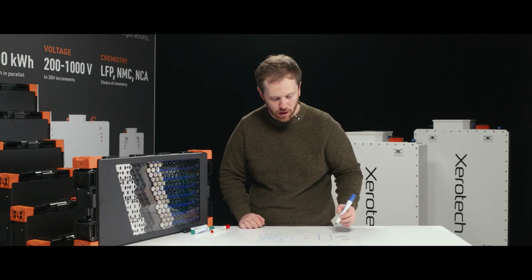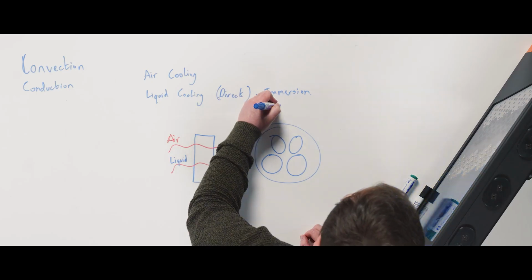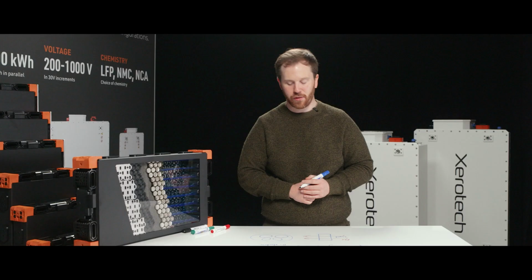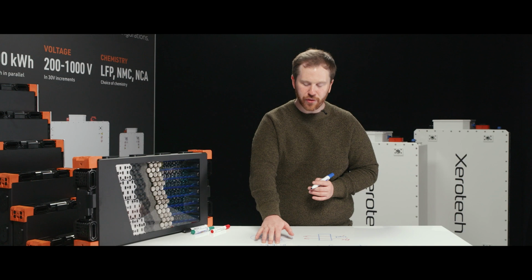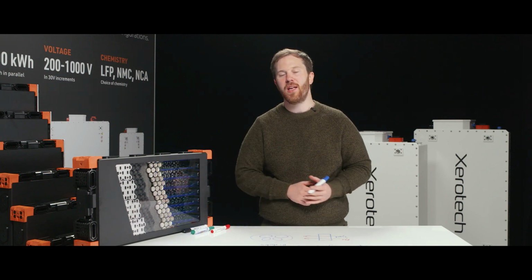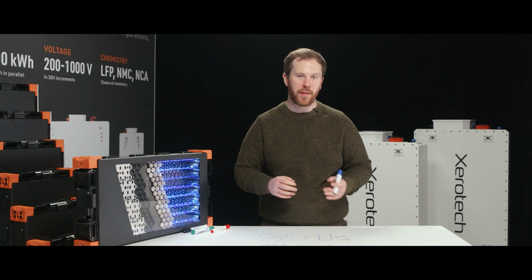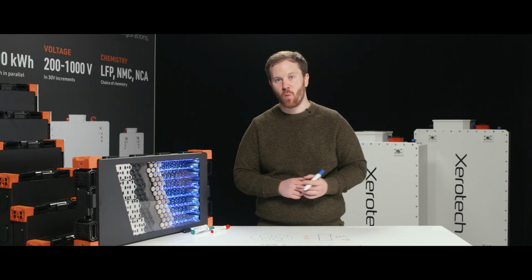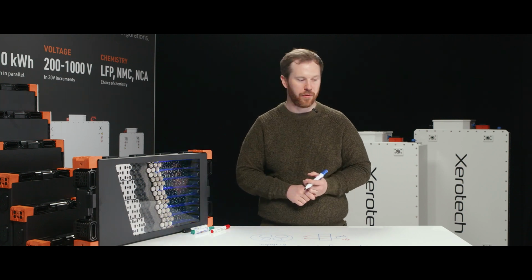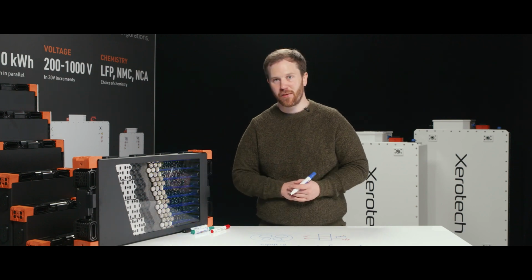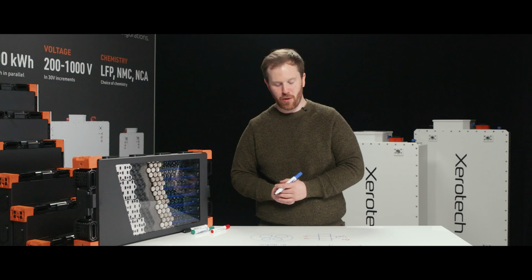Instead, they use something called a dielectric. Basically means it doesn't conduct in most cases. The dielectrics, unfortunately, have a much lower heat transfer capability, usually about half, if not lower, than that of water, and have much worse thermal properties in terms of thermal conductivity and other factors. They're generally more viscous as well, which means it takes a lot more power to pump them.